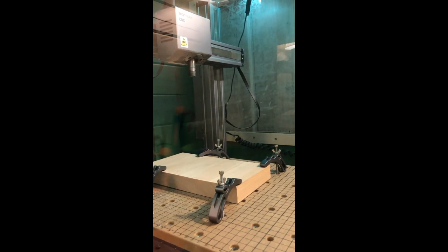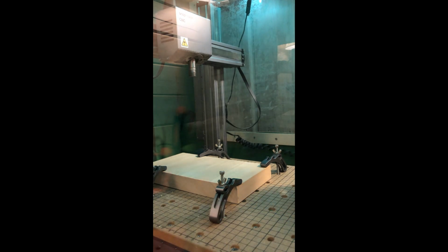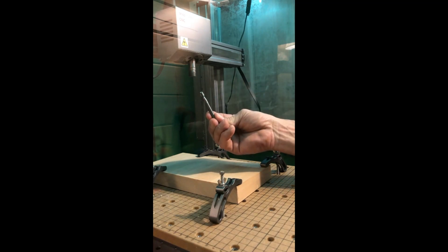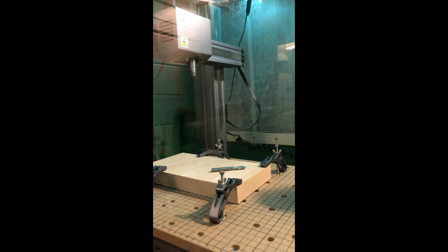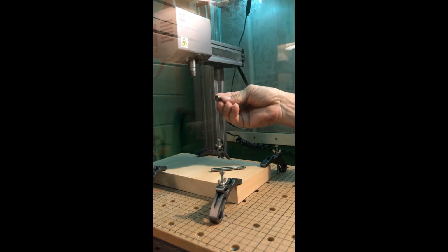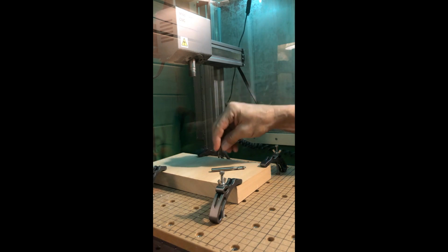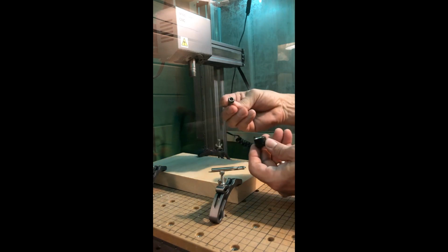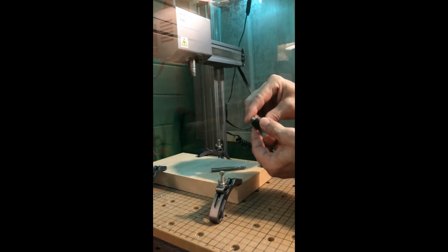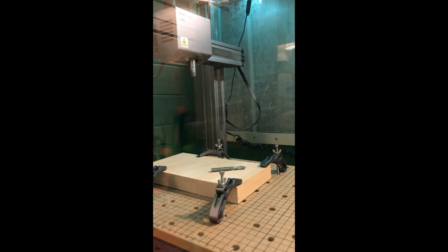Okay, now what we're going to do is set this up so we can cut this with a 1/4 inch bit. Quarter inch flat end mill, 1/4 inch ER11 collet, and then the nut. You want to take this and put it in here, cone side in this way, and push it in there so that you hear a snap, just like that.